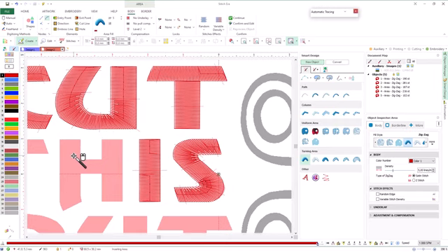This region of the image, the letter H, presents a situation similar to that of the letter T. Here we should use 2 cut lines to divide the contour into 3 contours, one for each vertical region and one for the horizontal region. However, we will use a more automated auto trace mode, called Auto-Complete. Select Auto-Complete and click to capture the contour. Note that the definition of geometric elements is disabled in this mode. Press Enter and the system will complete the creation of the object.